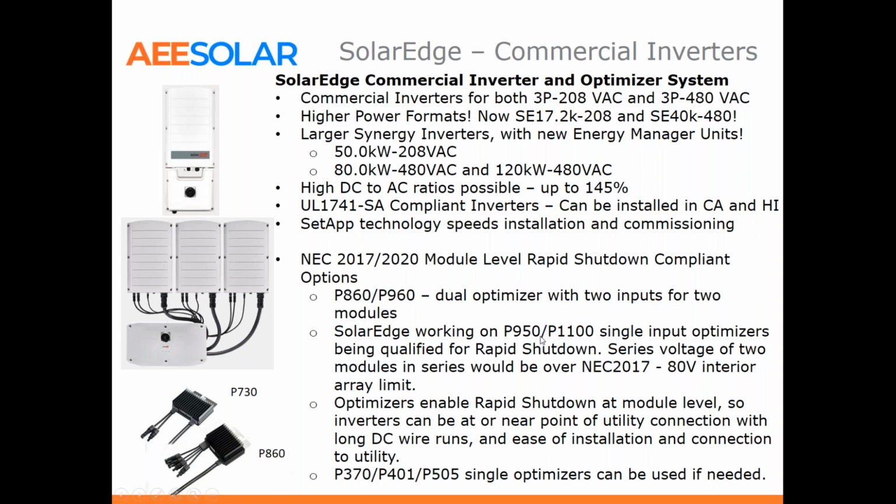The SolarEdge site design tool, the string design tool at the SolarEdge website, really should be used for just about every project to make sure that you're getting the right optimizer and pairing it with the modules that you're choosing.